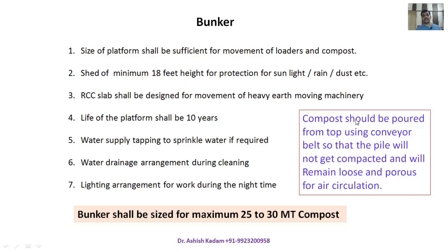We are providing perforated holes in the slab, so sometimes those holes or small crevices or small spaces which we are providing in the slab get closed because of the compost, so we need to open them, otherwise proper efficient air circulation will not happen. So we have to use the water source for the cleaning, so there has to be a tapping available.